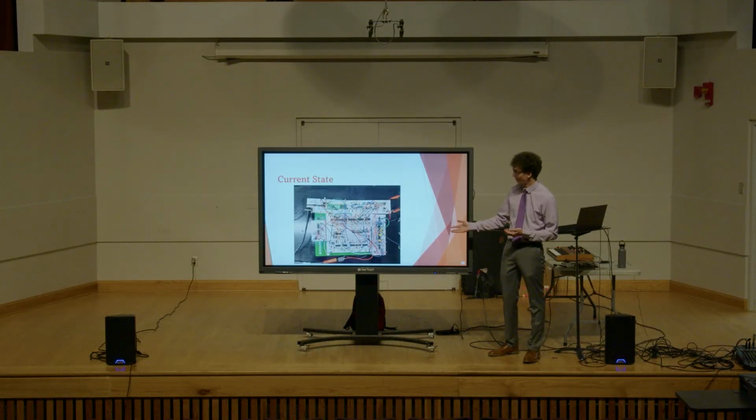The circuit to the right is the filter modulator. The top right circuit is the envelope generator. The top left circuit is the Pico control board with the DAC on its right and also a MIDI connector implemented on it. And then the leftmost board is a second very, very basic oscillator core so I could have the sound of 2 oscillators running.